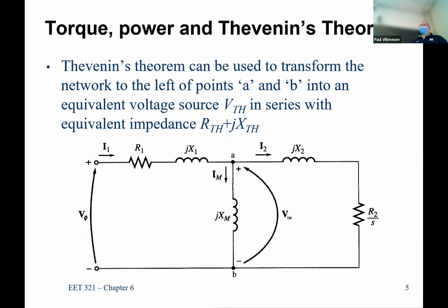We're going to do some equations, but remember, an equivalent circuit means that the results we get doing circuit analysis should match pretty darn close to what we would see in the real world. And remember, in the real world, the way we change the load on an induction motor is not electrical, but mechanical. You put more load or more torque demand on the shaft, and that's how you get more load.